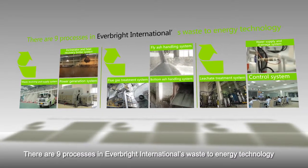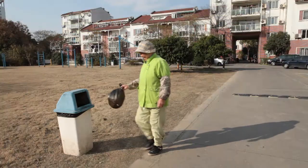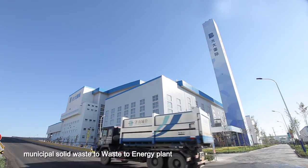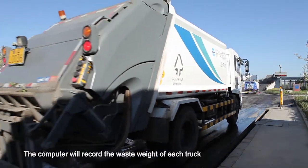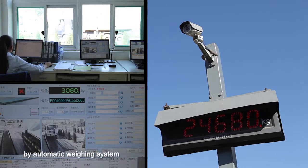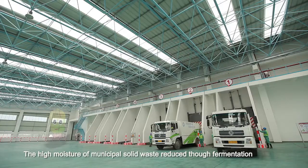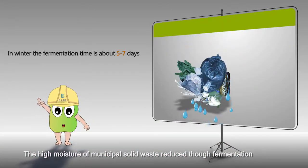There are 9 processes in Everbright International's waste-to-energy technology. Liaising with the local government, waste trucks transport the unrecyclable municipal solid waste to waste-to-energy plants. The computer will record the waste weight of each truck by automatic weighing system, and then the trucks unload the waste into the waste bunker. The high moisture of the municipal solid waste is reduced through fermentation.